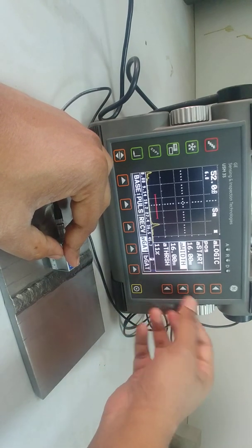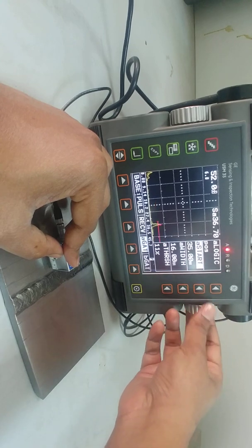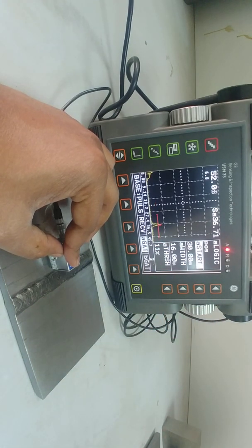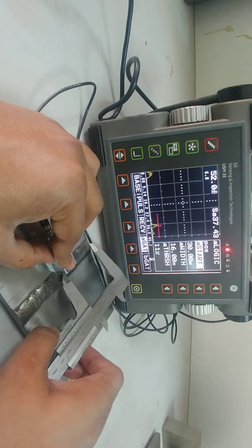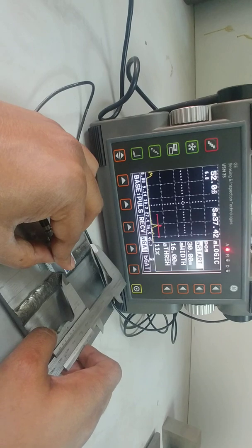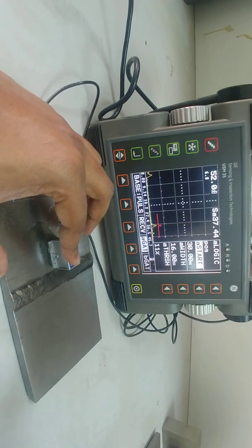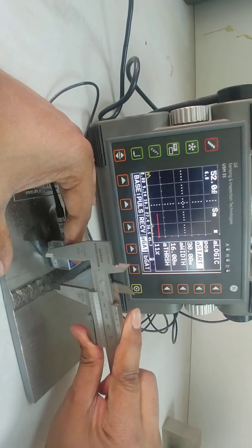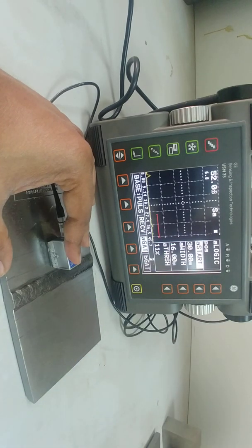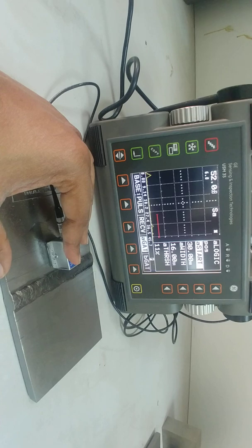Yes, you have one more defect. Let's move this one. Okay. So you have one more defect at 36.7 millimeter. Now if I see this from the top side, it's the center of the probe. This is 45.5 millimeter. And if I just calculate the index point to the center point, what is the distance? I'm having something like 24 millimeter.